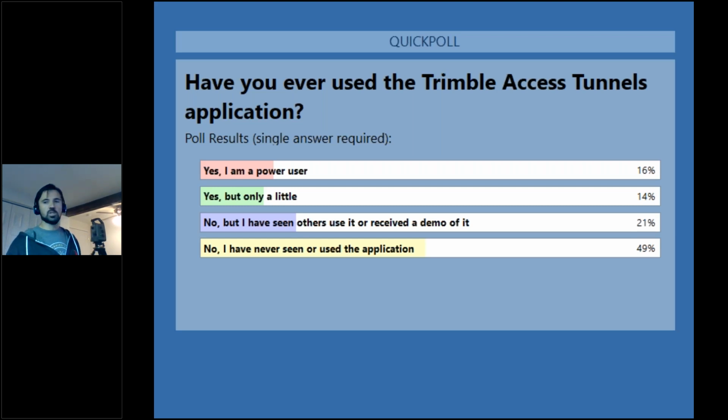In TBC or Trimble Access? He did not clarify, but I'm guessing TBC. If it's TBC, it's like any other element in TBC. So if you want to delete any of the templates or the shapes or any of that information, you can go and right click and delete that information.